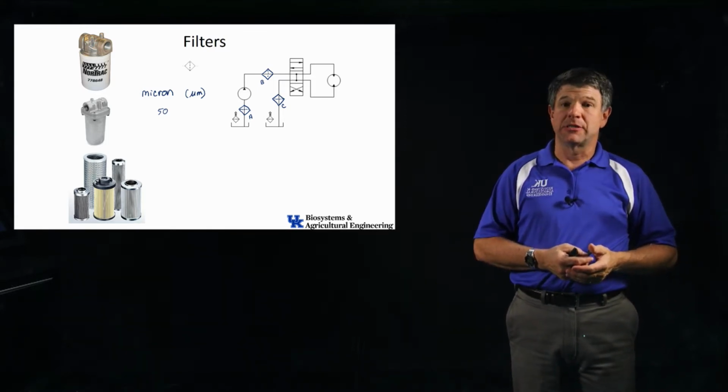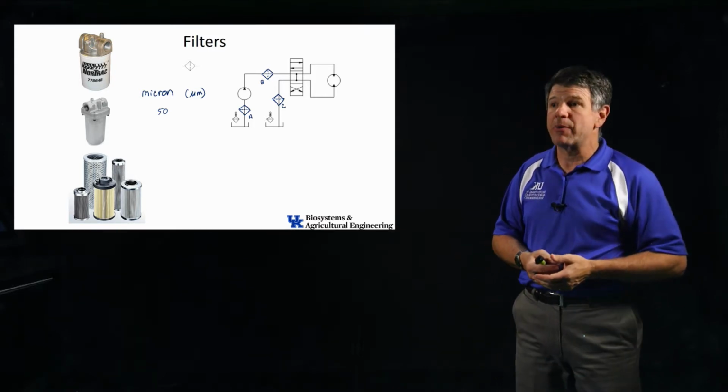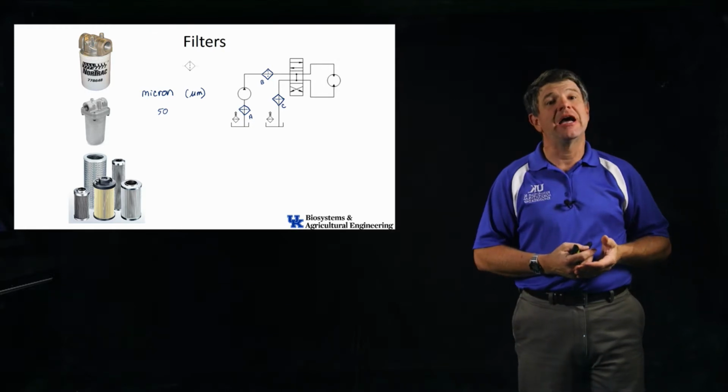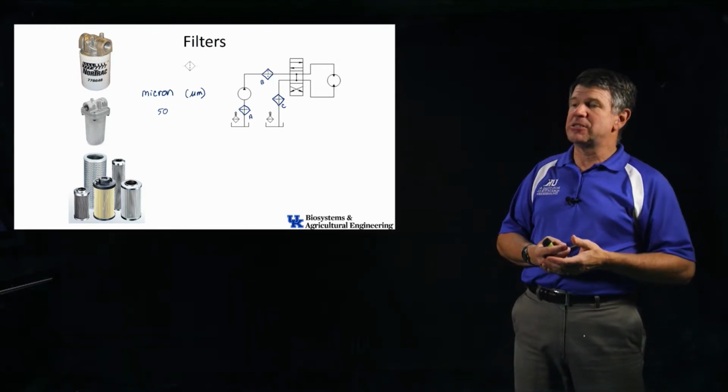The problem is, let's think about the pressure in that part of the system. So that's right after the pump. That's where I'm going to see the highest pressure, highest system pressure. So that changes the design of my filter.